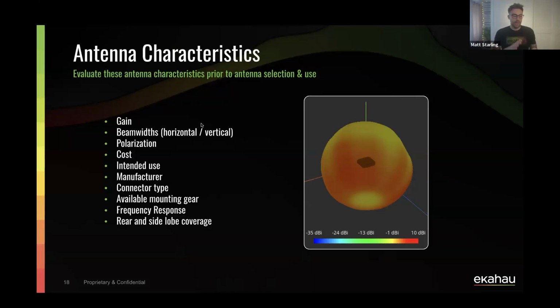And when you provide a floor plan to the installation team and you give some AP icons on a map, if you don't provide a good level of detail of how you physically want that to be installed, I've seen installers literally just take an access point, put it right up on the actual physical ceiling, and it'd be completely surrounded by all of this different metal and steel and other pieces of concrete, and that can attenuate and corrupt the signals coming from the access points straight away.